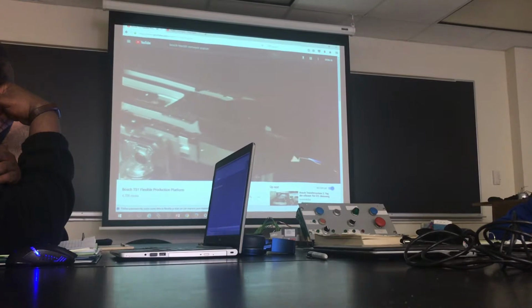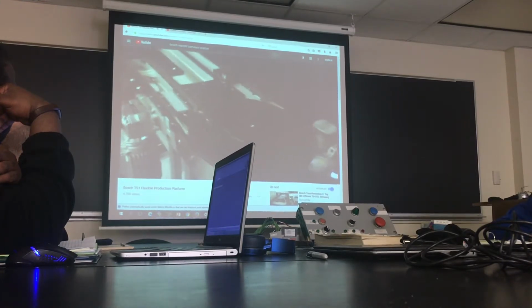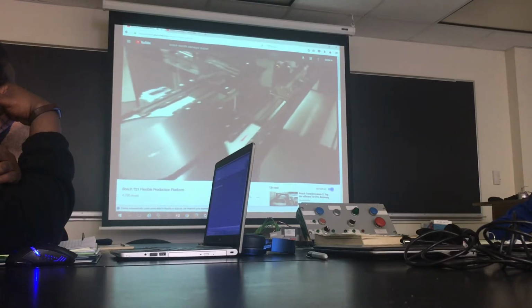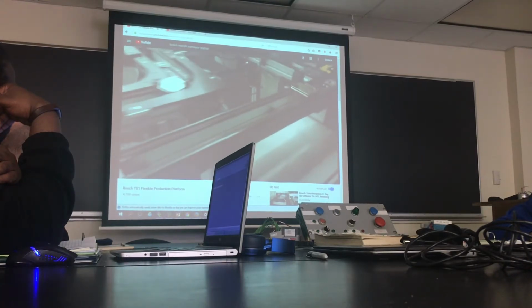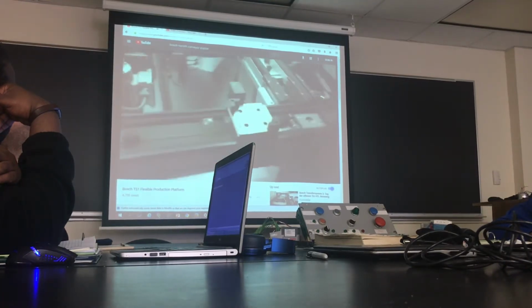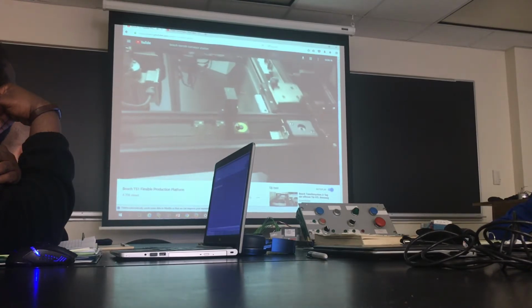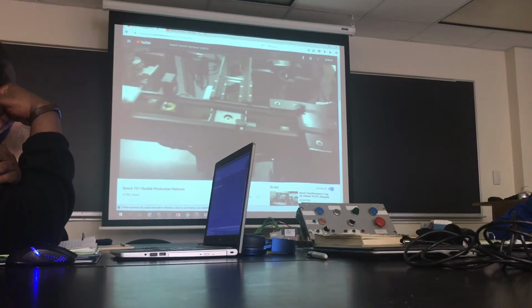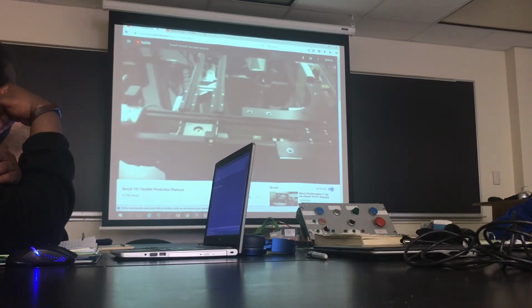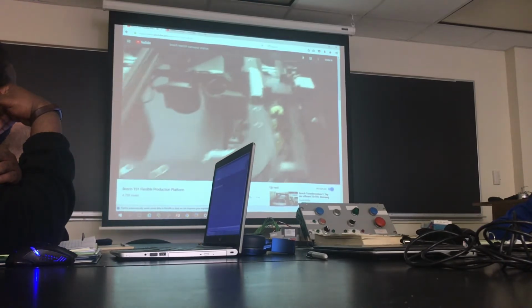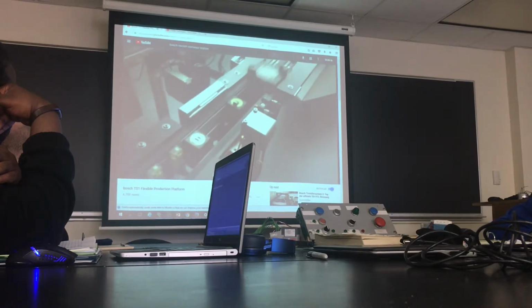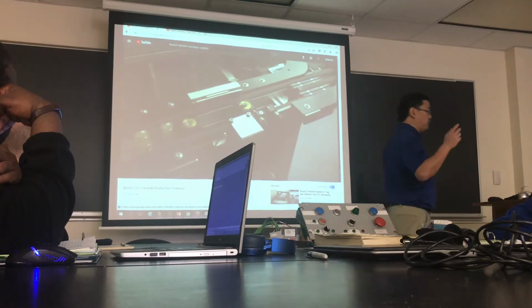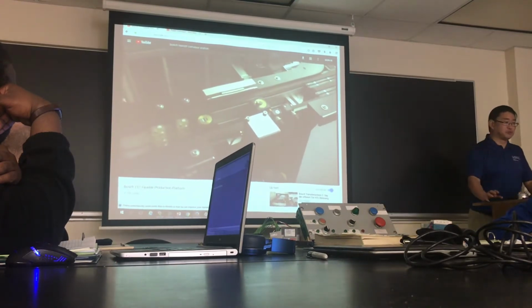I can now tell what pallet is in front of a workstation when it stops. And there's a read head right there, although it's a different style. So it's saying, is it product number 2, product number 3, what is it coming by? And without having to use a barcode scanner or RFID or something else, I'm able to identify uniquely each of those pallets that went by.